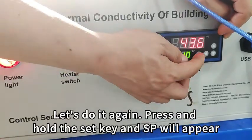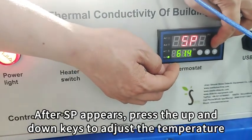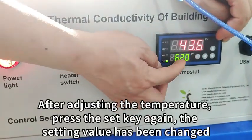This is how to adjust the set temperature. Let's do it again. Press and hold the set key and SP will appear. After SP appears, press the up and down keys to adjust the temperature. After adjusting the temperature, press the set key again. The setting value has been changed.